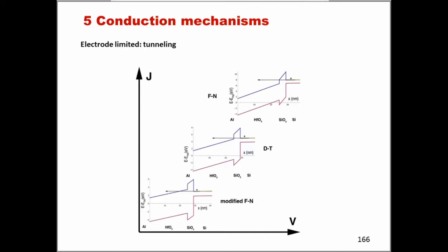So going back to modified Fowler-Nordheim, when we are dealing with a dielectric stack, the question is, okay, what mechanism will I see or will be at play at which voltage? So this diagram here that I've made is exactly there to help you realize what should be dominant at which voltage values.